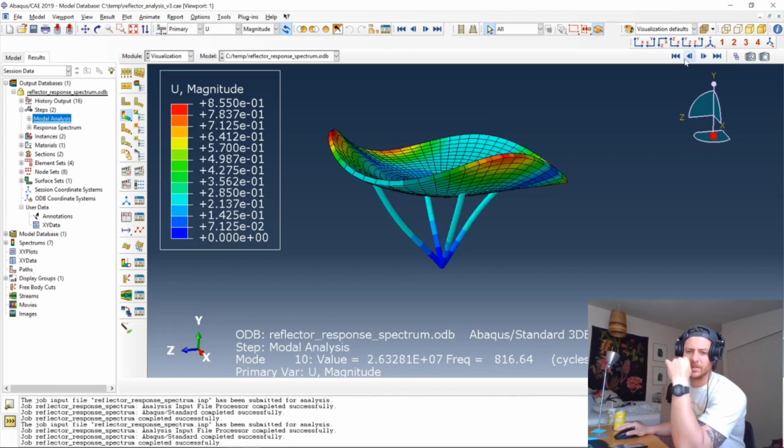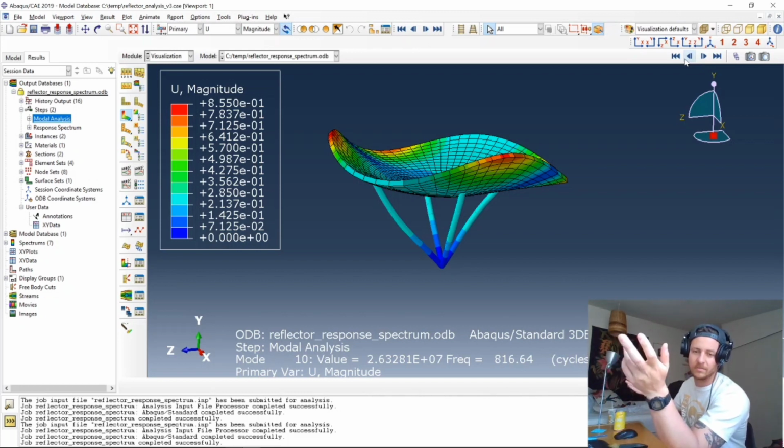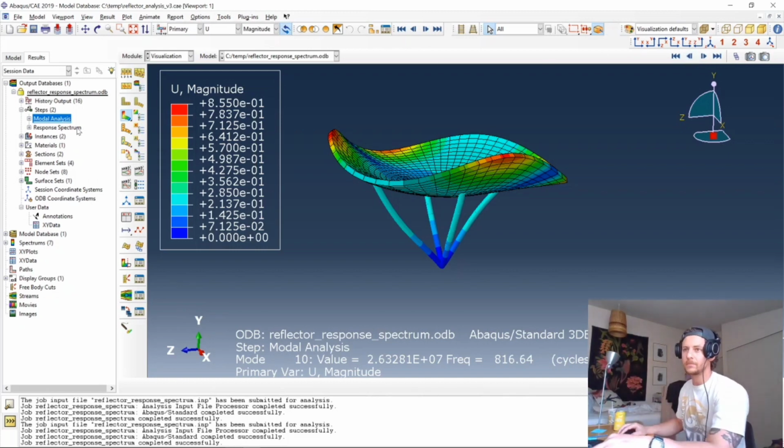So this is exactly why we truncated that acceleration SRS tabulation to 1,000 hertz and didn't take it out to 10,000 hertz. If I would have requested 20 modes or however many modes that has modal content out to 5,000 hertz or something, we would want to accommodate that in the tabulation of the acceleration SRS.